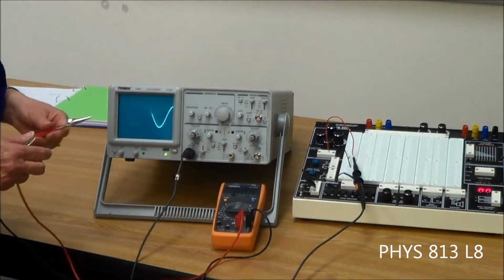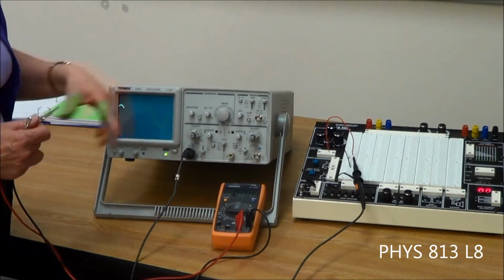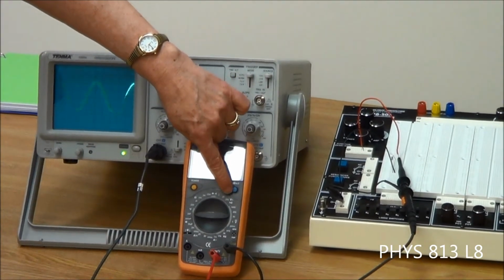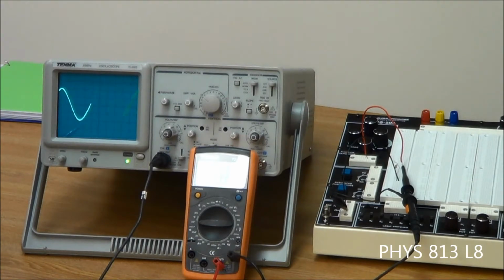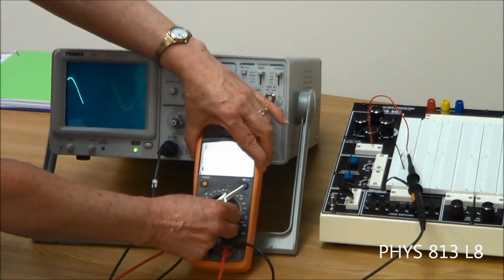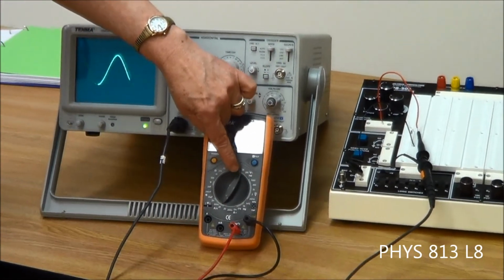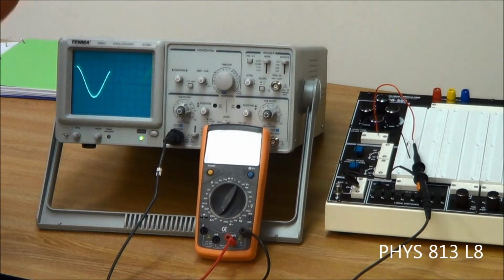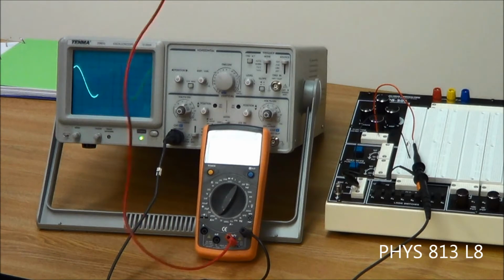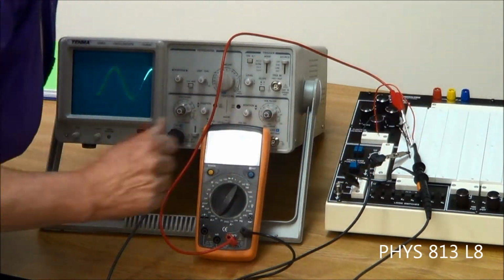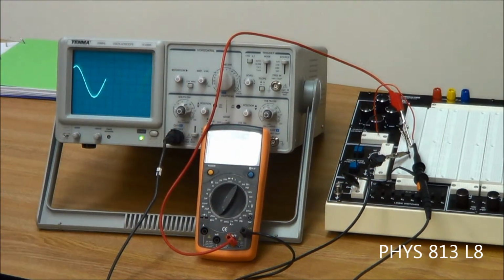Voltage, I've got it on 20. Make sure that you have it on the voltage. Oh, that's convenient. The voltage that has the little wiggly line, that's the AC voltage. So we know it's 2 volts. I'm going to put it on 20. Also make sure that you're looking at the end that has the little arrow on it, because if you use the other end, it doesn't work. So we have 20 there, and now I'm going to measure across the resistor. So I'll put that there and that there, and we get about 1.35.